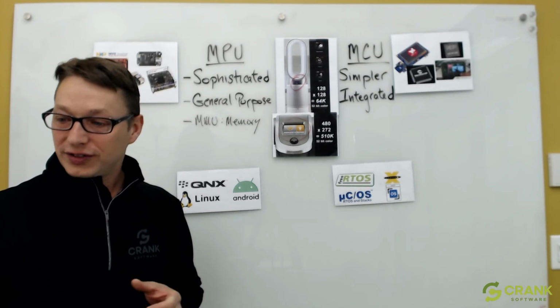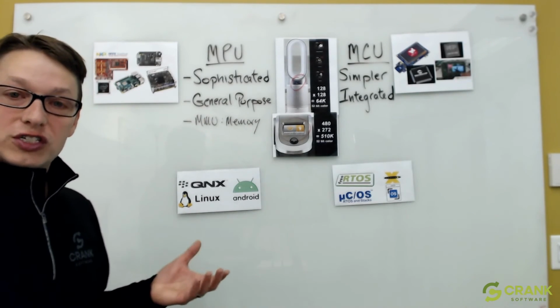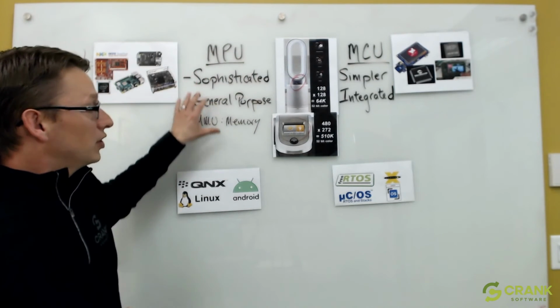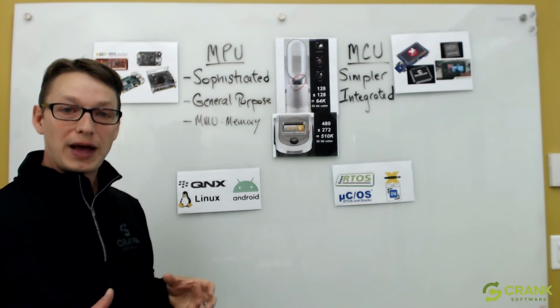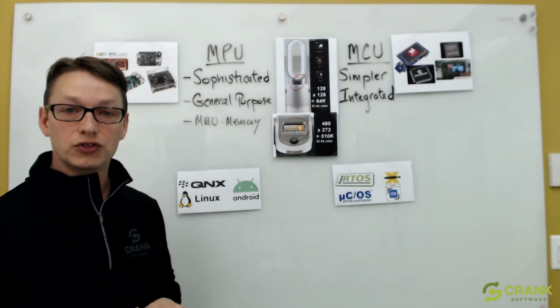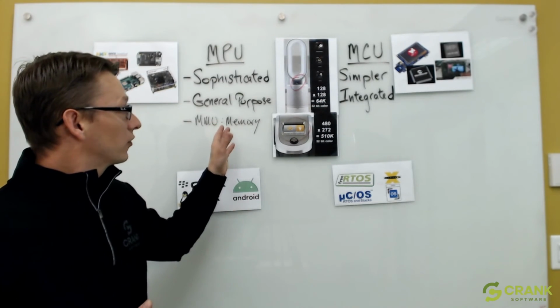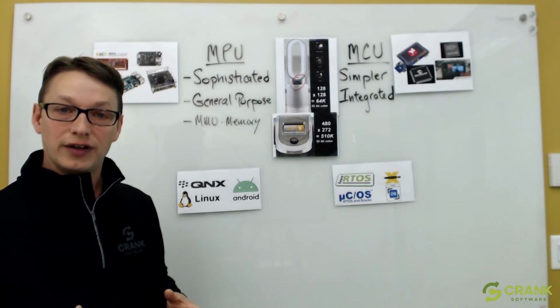One of the other questions that I've seen is, what about SOMs? So SOMs, or system on modules, are really an attempt for the MPU configuration, right, to take more of its functionality and package it up into a bit more of an integrated solution. So when I talk about crossover type solutions, while a SOM is not an MPU or an MCU, it is a packaging story, right?